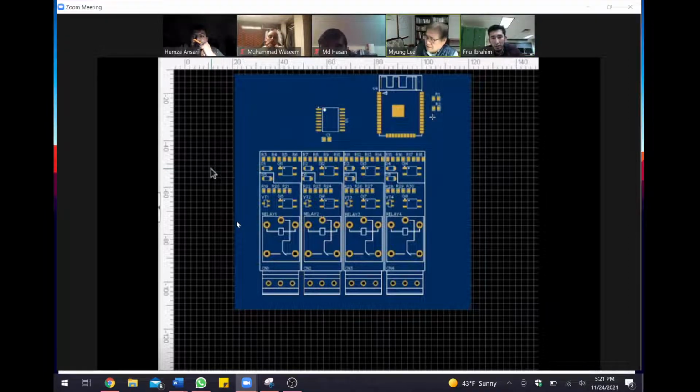And by the way, now I see the wire path, the track from the connector to the components, going next to the relay. This is long, you traced it. And so when the relay is on and off, there might be some sparks which generate a noisy signal. That noise may get into this PCB path?